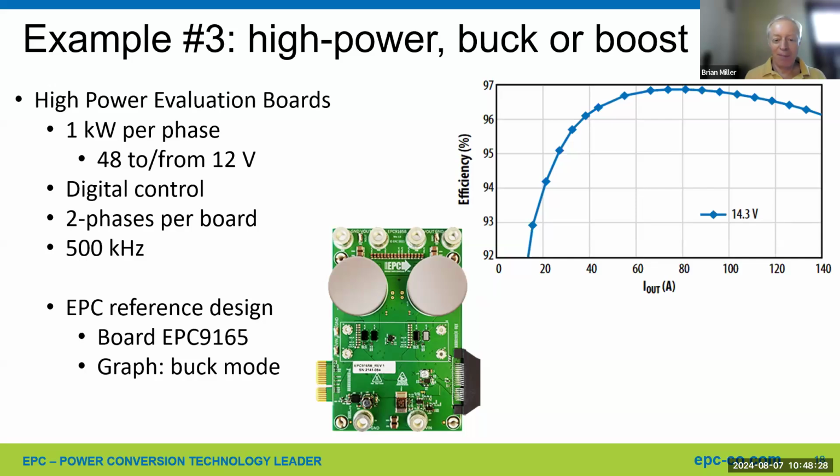If you put something on top, like a heat sink or a heat spreader, all the GaN FETs are less than 1 millimeter. So a little thermal pad sits on top of here. These take the mechanical stress, and then the heat sink goes on top of that. Either heat spreader or heat sink will go directly. And that's probably the best way to get the heat out the top, using a heat spreader or heat sink, and also using external spacers to keep the pressure directly off of the GaN FETs. Let's see, that was for heat.